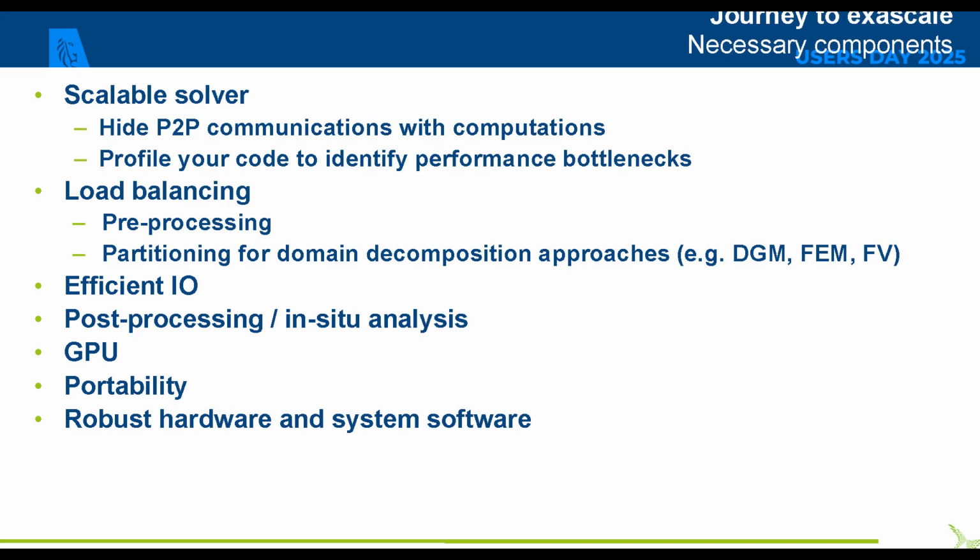A second, well, having a scalable solver is fun to work on, but this is not what is going to guarantee a scalable simulation. You need also to pay attention to the load balance of your code, and usually this is handled during the pre-processing. I'm more familiar with domain decomposition approaches, like finite element methods or finite volume methods. These are based on the decomposition of your domain, represented by a mesh, into mesh partitions. So I'm going to mainly focus on this kind of decomposition.